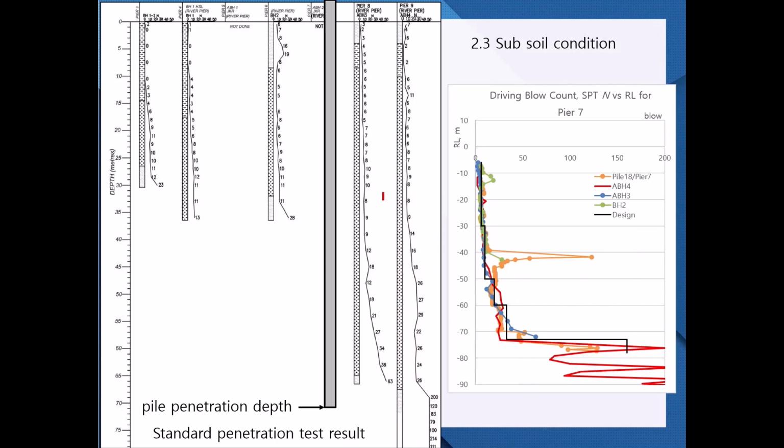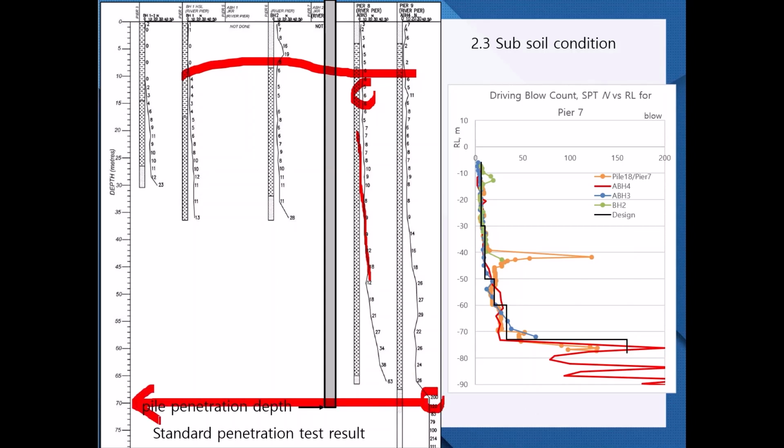The soft clay on top is about 10 meter, and below the soft clay is loose silt with increasing SPT N starting from about 6, increase slowly to SPT N more than 50 at about 70 meters.